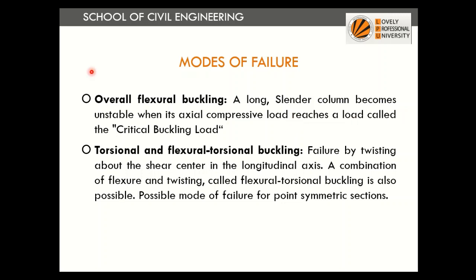Then modes of failure. There can be various modes of failure. We have already discussed that. Long columns will have buckling and torsional failure, whereas short columns will have crushing failure only. So as a designer, we are more concerned about buckling failure because the buckling load is quite less as compared to crushing load, right?